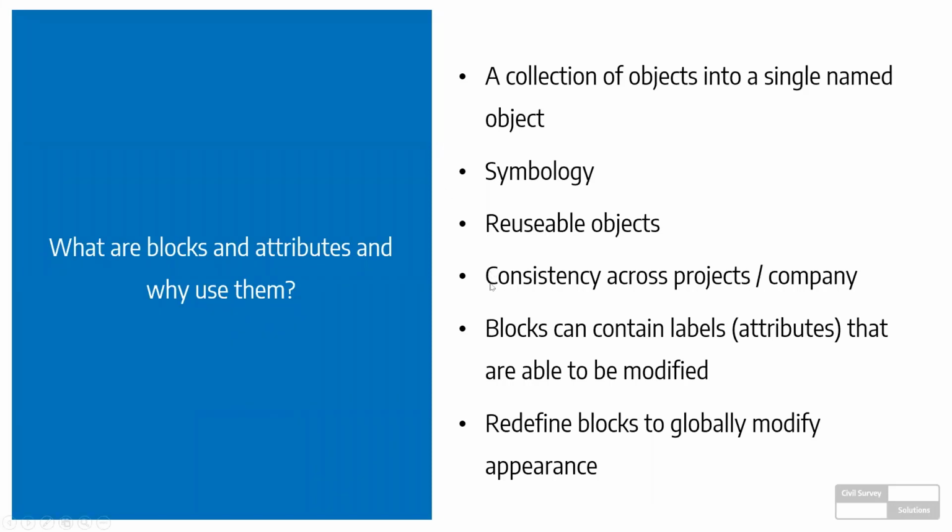And if you do write your blocks out to a block library or something like that, those blocks then become available to insert into your other projects. So your company may have a group or a library of block objects that they've provided for the company, and it will probably consist of trees and different symbology and things like that. Some blocks will come in full scale, some blocks will be scalable, but that will all be set up by your company.